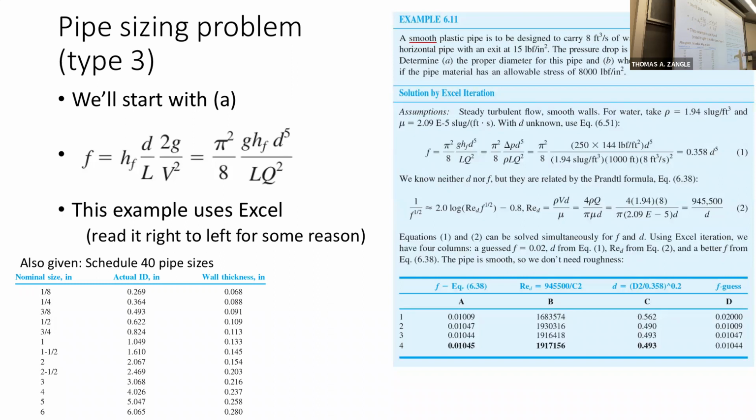So what we're seeing here is the impact of A squared, right? Remember, if we're relating velocity to flow rate, Q is equal to V times A, right? And so that area is going to give us a D squared, and then this whole thing is squared again. So that's how we end up with a D to the 4th times this already D, and that's how we end up with D to the 5th, right?